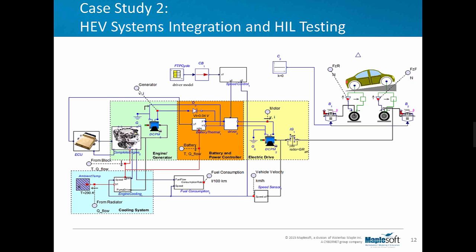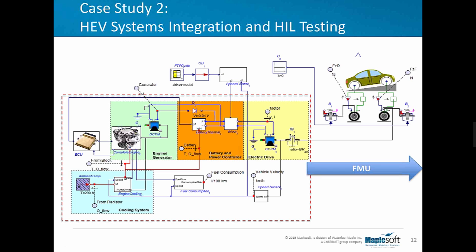It's also important that the simulation environment be capable of testing the pieces and giving confidence before exporting the FMU to the integration environment. The model incorporates the mean value engine, power electronics and thermal effects, the battery system, and electric motor. So the system that incorporates the powertrain, the electrical system, and battery was isolated and causalized, and the FMU was generated from it.